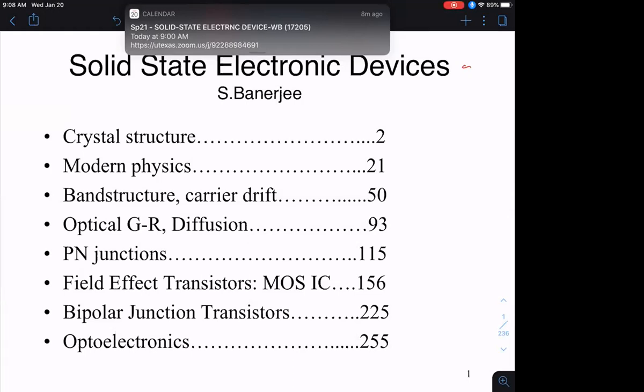Okay, so we'll spend about 4 or 5 lectures on that. The reason is the p-n junctions are fundamental to many other devices, okay? And some of those will be discussed in the final chapter 8, which I call optoelectronics, where you'll see that depending on the way you bias a p-n junction, you get all kinds of fun device structures out of it. If you forward bias the thing, you get what is called a light emitting diode or a semiconductor laser.